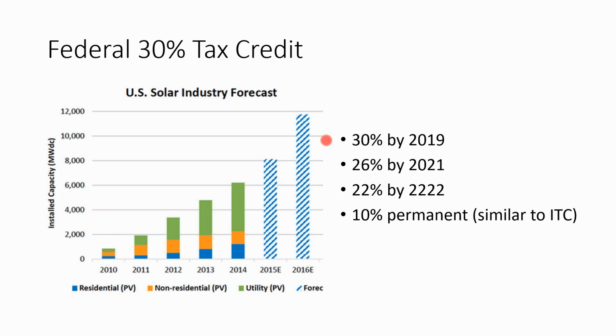What you have to do in this circumstance, and this is more important for the larger commercial facilities, I'd say, but you have to track all of the energy coming out of the array and all of the energy that is outflowing onto the grid and all the energy that is being charged with the battery.